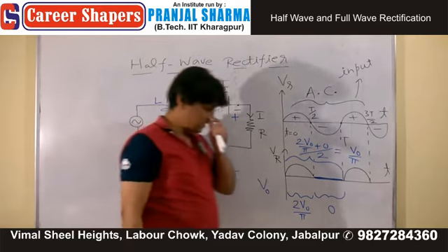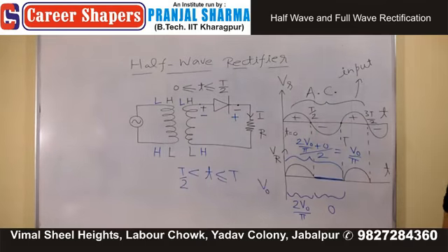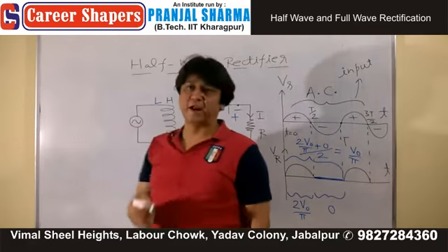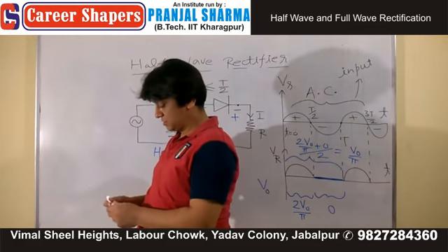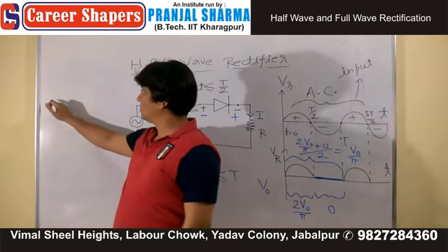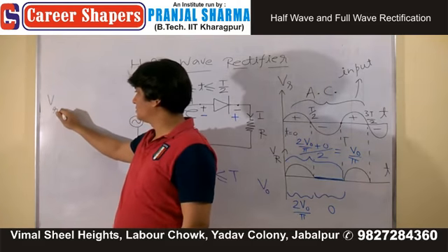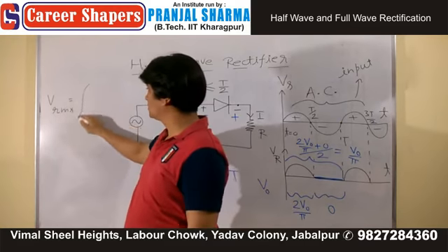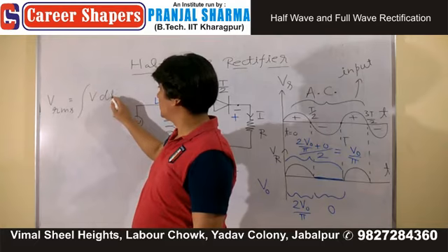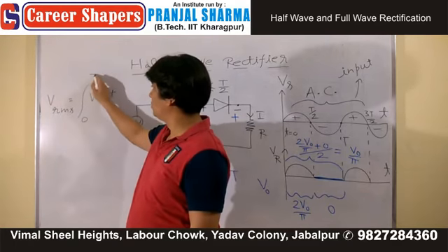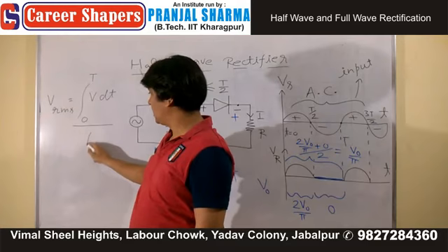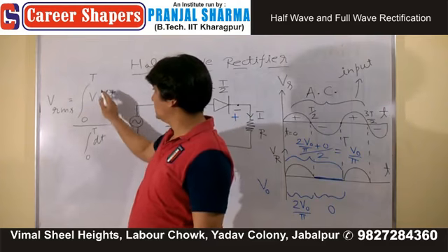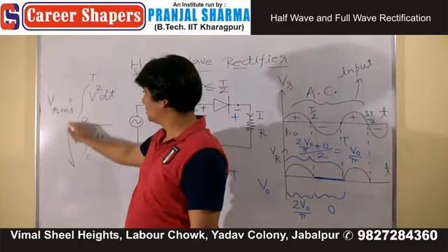That's not a question of semiconductor, it's basically a question of alternating circuit. And I hope you remember how to find RMS and all these things. If you are interested in VRMS or IRMS, you go for the integral of V squared dt from 0 to T, divided by the integral of dt from 0 to T, and then the root.